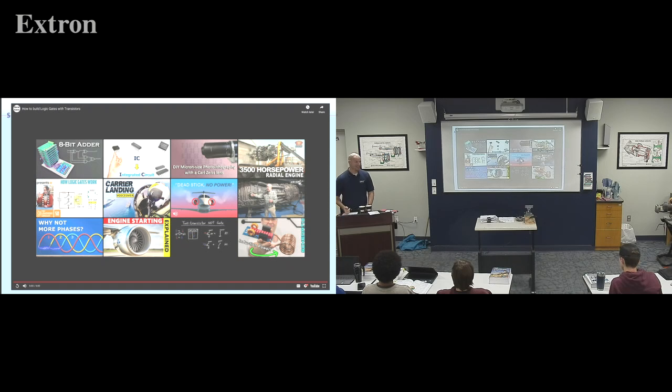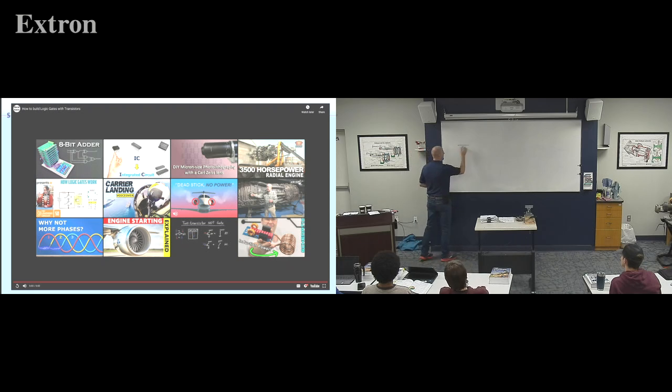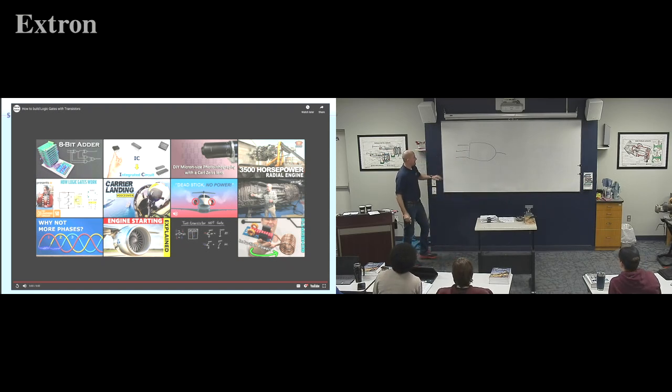That's a good one, yeah. I was thinking landing gear. So when we've got 3 different landing gears, if all 3 are down, we might want to turn a light on. Well, that would be an AND gate, right? So now on the back end I've got 3 legs. An AND gate, that's the nice friendly one. An AND gate would say, if I've got all 3 of them on, yes, I'll give you a signal out here. So if I get a signal, I'm going to turn a light on for the pilot that says your gear is safe.